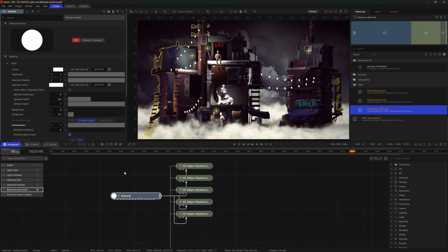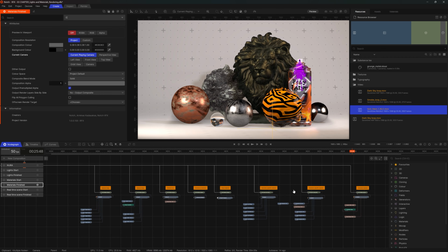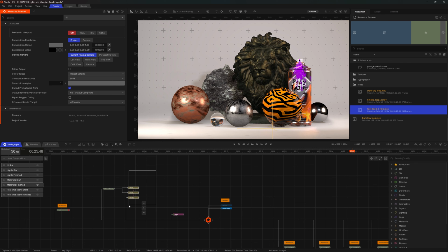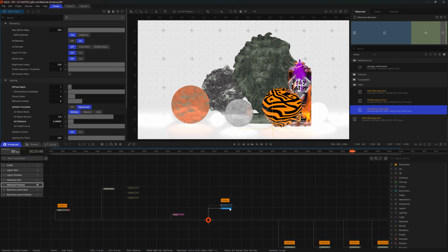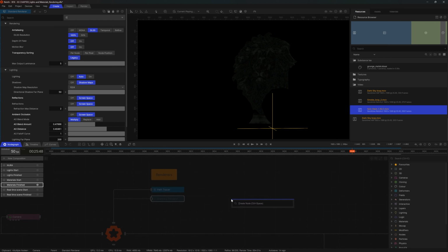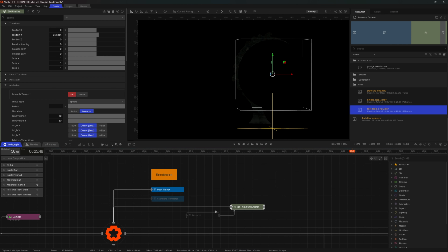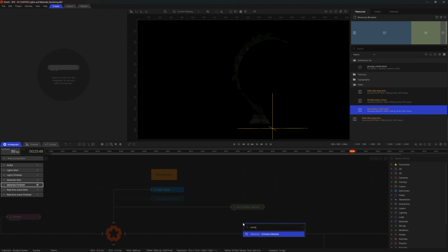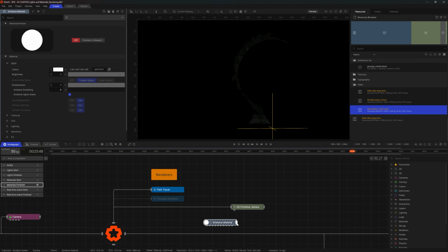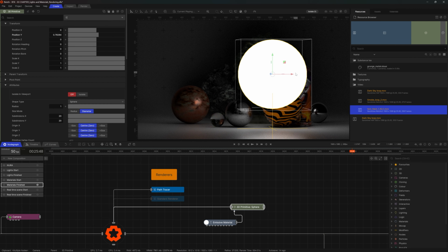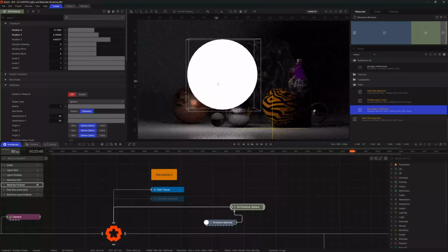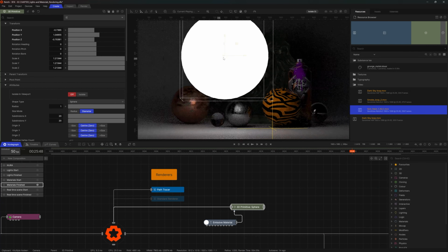Now, standard render does not support global illumination. However, were you to switch to path tracing, this then becomes emissive. Let me show you that in a materials finished setup in practical terms. So first of all, I will disable the lighting setup that we have here. I will switch to path tracer and I will add a primitive. There we go. It's all blacked out because we don't have any light source. And for that, I'm going to use an emissive material.